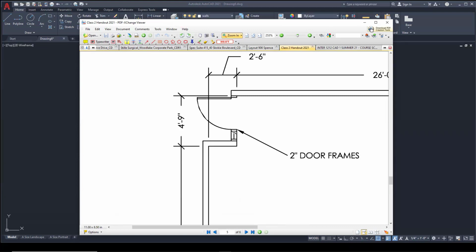And when we're drawing a glass window, we generally just draw a line right down the middle from the edge of that mullion to the edge of that mullion. And that represents a glass line. Whether or not that glass is actually there or on the edge or on the inside, generally the convention is to just draw that glass line right down the middle. Okay.